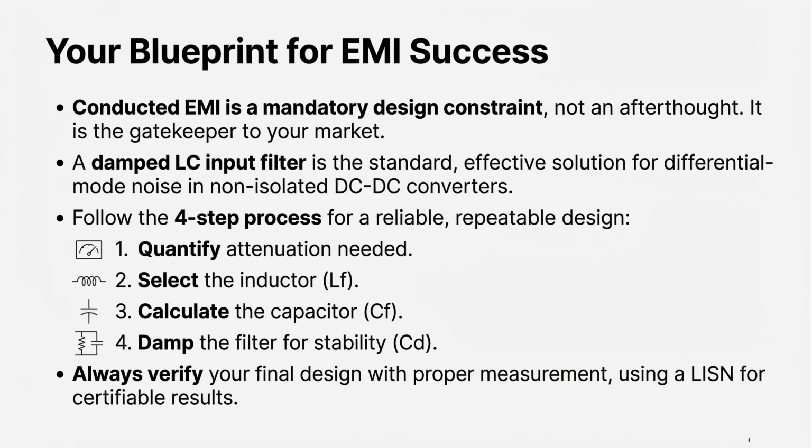To summarize, conducted EMI is a mandatory constraint. Use a damped LC filter for differential mode noise. Follow the four-step process for design, and always verify your final design using a LISN for certifiable results.